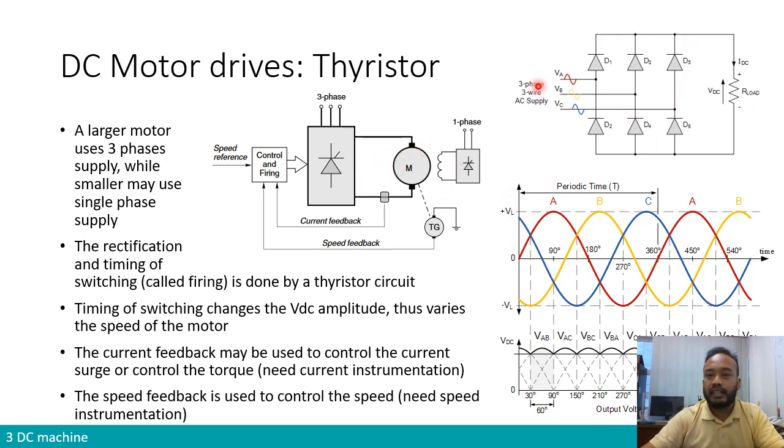So all the circuitry is basically the thing that is symbolized in here, right? So we have the three phase coming in, and in the output we have basically a single phase DC. So inside here is basically this circuit, and this is the input, and what we get in output is this waveform. This waveform is a pulsating waveform. The value of the VDC at the end will not be equal to the maximum voltage of this AC. It will be at a certain value which we could call VDC average. Okay, so there is a calculation to find that.